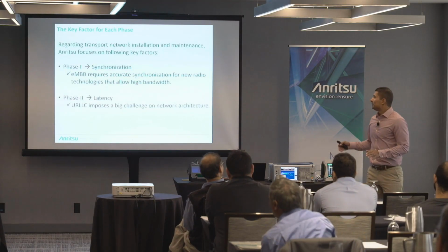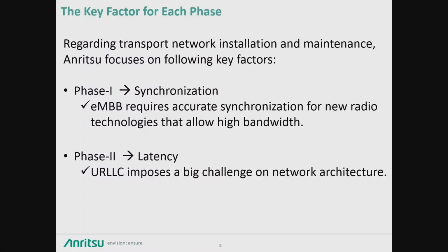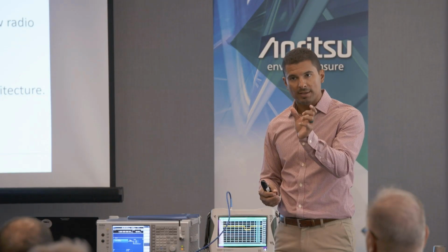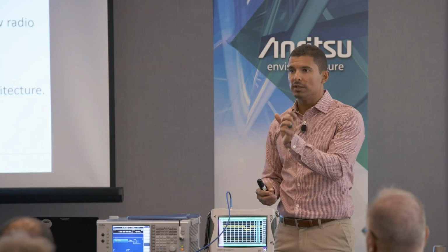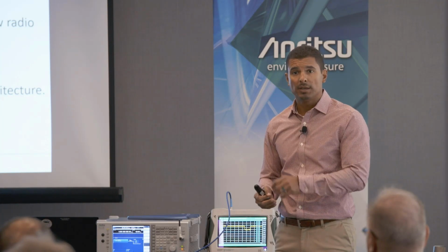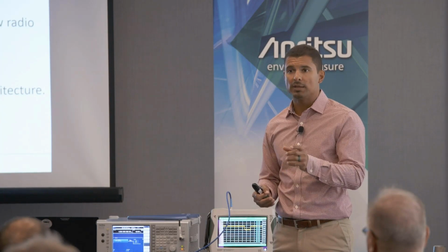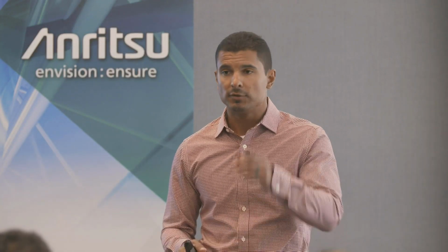So what does that mean? First part of phase 1, as we're working with our customers today, and now I'm going to start talking about the real world scenarios and the type of applications that we're testing today. When it comes to enhanced mobile broadband, it has everything to do with, as Jeff and I both talked about, TDD, time division duplexing. And as Jeff also mentioned in his presentation, when you're looking at the time slots, everything is in relation to time, in microseconds. And if you are just a few microseconds off in any direction, you're looking at a different time slot. And if you're trying to transmit when they're receiving, you lose everything.